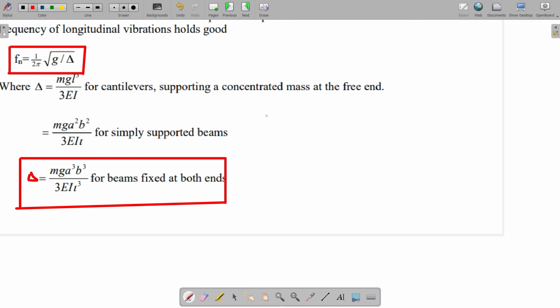First of all, we need to find out the value of moment of inertia of this one, because moment of inertia is not given, right? Moment of inertia can be calculated as I equals pi d to the power 4 divided by 64. After putting the value of diameter in this equation, we will get the value of 125.663 into 10 to the power minus 9 meter to the power 4, right?